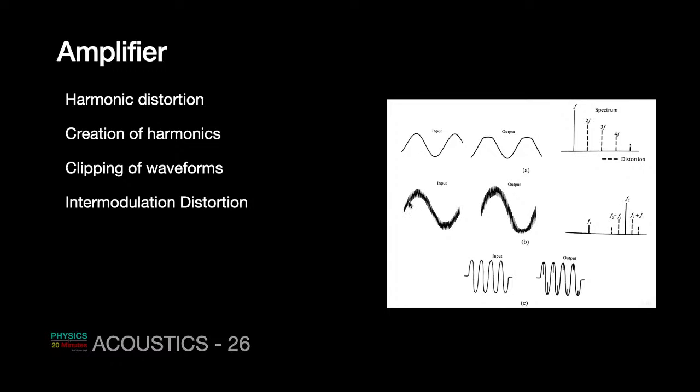The other is the intermodulation distortion. So this is my output. There is a base low frequency which is modulated with a high frequency, or whichever way you look at it, a high frequency being modulated with a low frequency. Even when this happens, there can be some distorted output, and instead of getting just one sideband, you can get a number of pairs of sidebands, and this could be another source of distortion. These are called sum and difference frequencies.